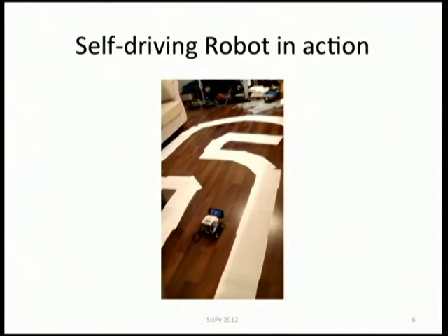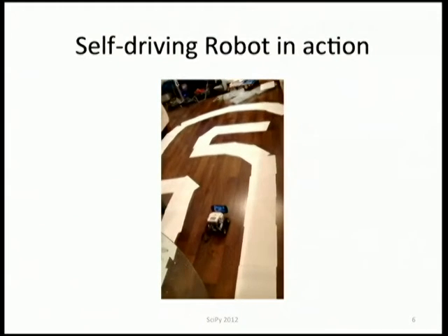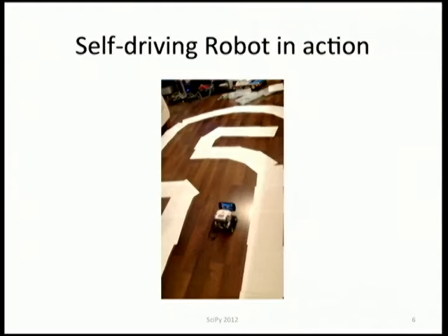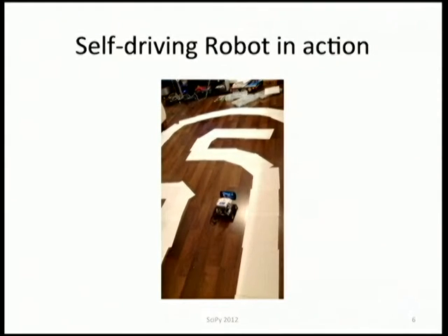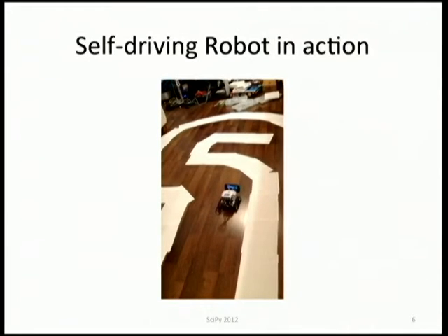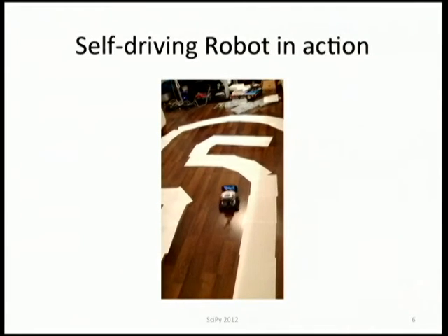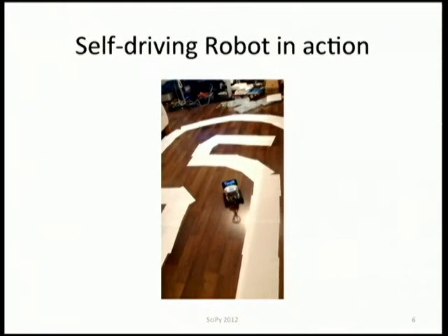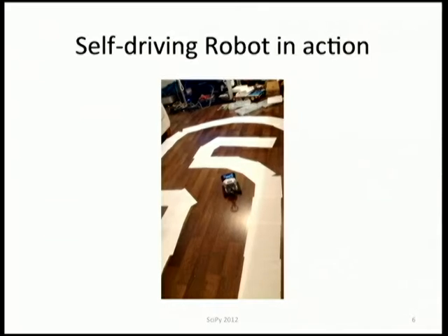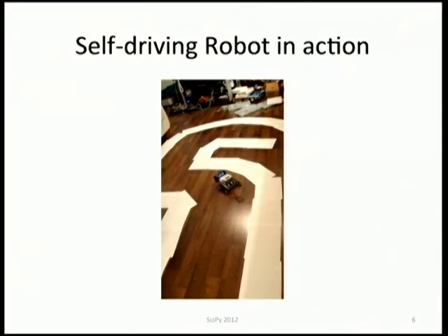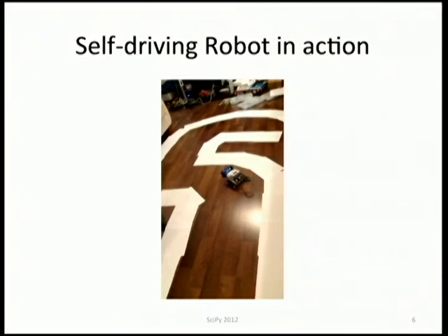So you can see that the robot is moving in spurts, and that's nothing fundamental. It's just the way I built the robot. There's a 3-second sleep between every action, and the reason that's there is not because it takes so long to activate the neural network. The neural network activation is actually pretty fast. You have to wait for the robot to stabilize and for the camera to stop shaking. Otherwise, you're going to get blurry images. So you can see it took that corner.